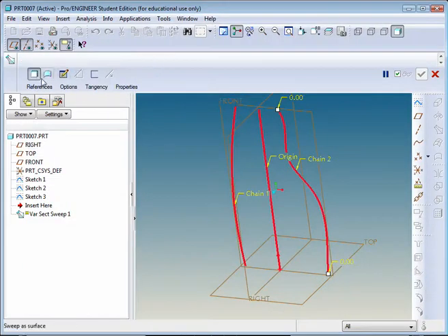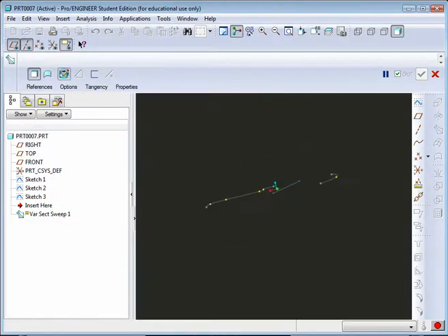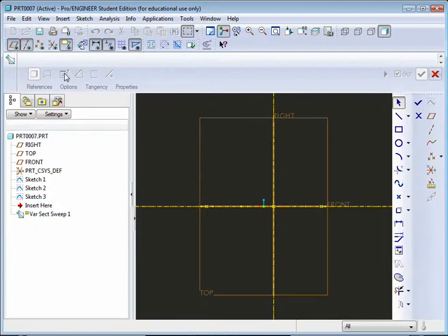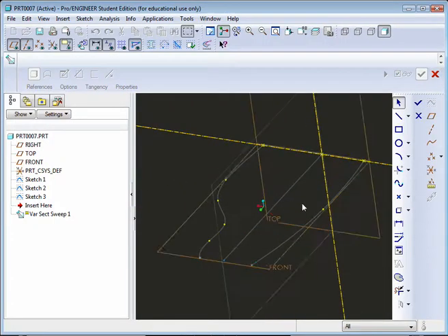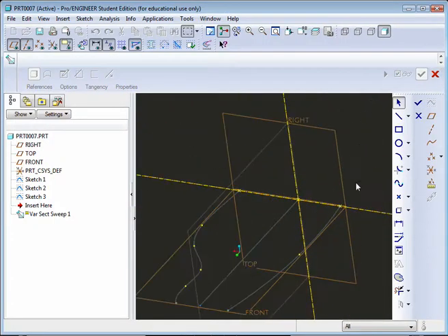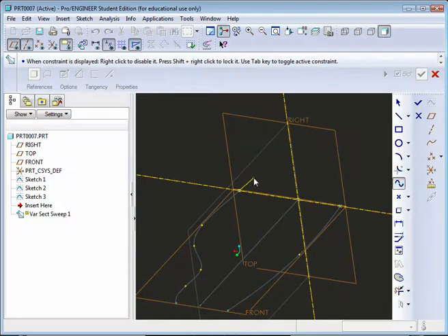So click on solid and then create sweep section. And if we rotate, you can see our plane is actually picking up on the right plane at the base here. And from that, we could take our spline tool and come off of those points and generate our geometry this way.